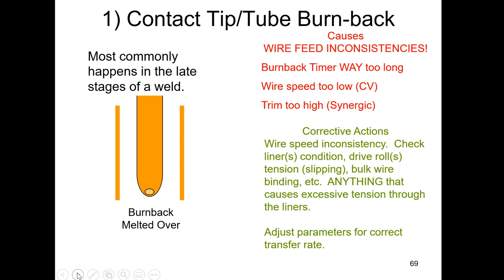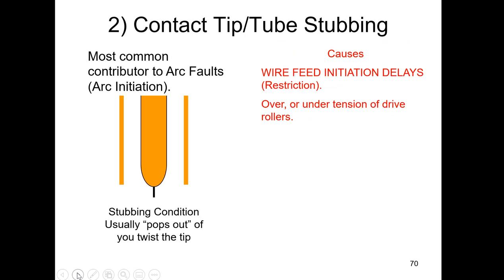And now, as soon as you've done all that, you've changed it, remember to check your parameters and get some cross sections done. Right? Things change, and sometimes people have made parameter changes to compensate for a problem. If you no longer have the problem, don't always immediately assume everything is going to be fine. Go back and get some validation done and make sure it's all done correctly.